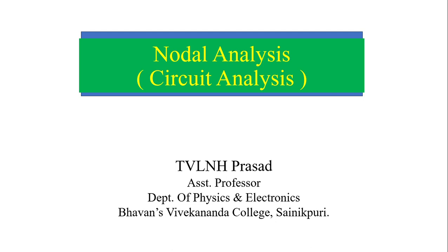Nodal analysis, which is part of circuit analysis. In this video, we are going to discuss the nodal analysis technique. This is one more technique, an analysis mainly using the nodes. Nodes are nothing but the junctions, and we apply KCL, which is Kirchhoff's current law. We get some equations, we solve them, and we use those unknown values to find the remaining parameters of the circuit.